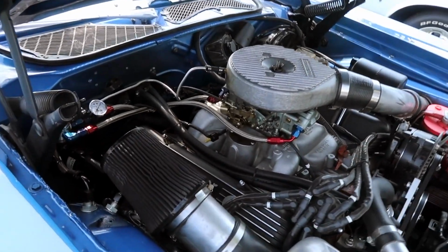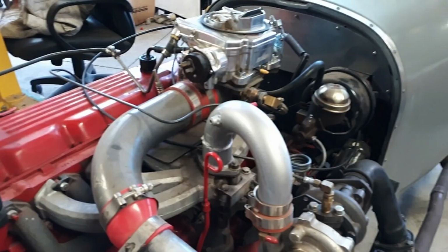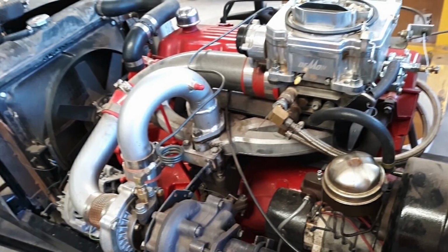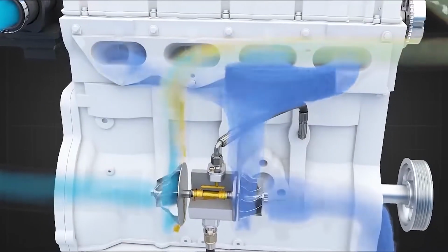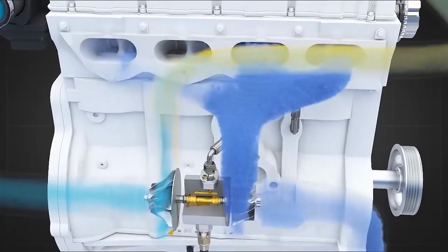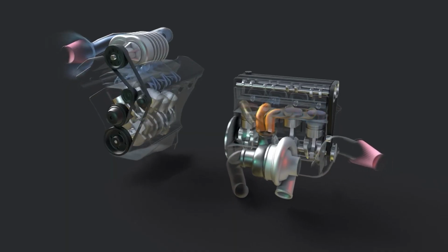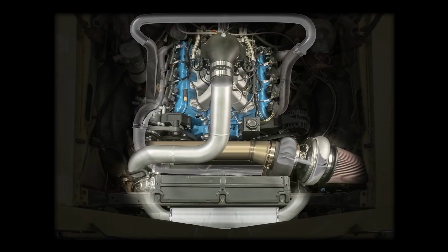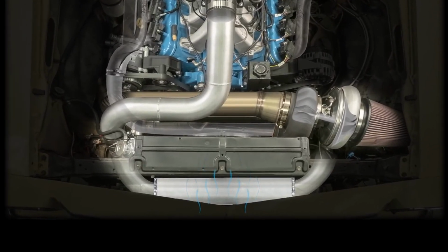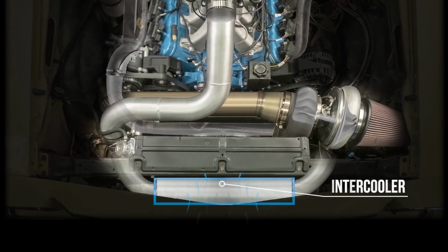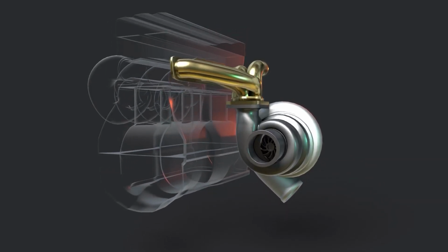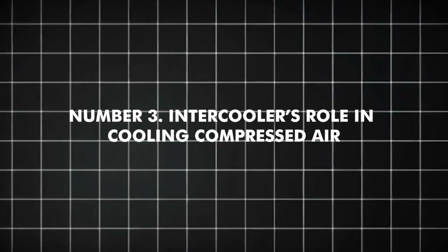By channeling the exhaust through the turbine, turbochargers convert exhaust gas pressure and heat back into useful mechanical energy, powering the compressor to increase intake air pressure without additional fuel consumption or mechanical load on the engine. This recovery of waste energy improves overall engine thermal efficiency, contributes to better fuel economy, and reduces emissions by allowing more complete combustion.